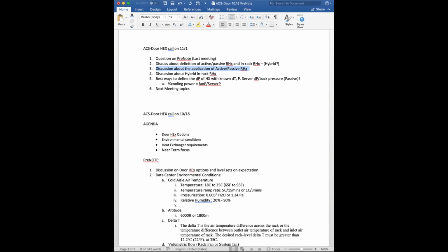So, Ronald, I think you can look at it both ways. If you're talking about dealing with the remaining 20% of the heat load using perimeter crawl units, the downside is you're still maintaining quite a bit of air cooling infrastructure. Naturally, a rear door heat exchanger is also, in a way, an air cooled approach, but it's close coupled. So to your earlier point, the paths of air travel are much shorter, and really there's a big economic benefit